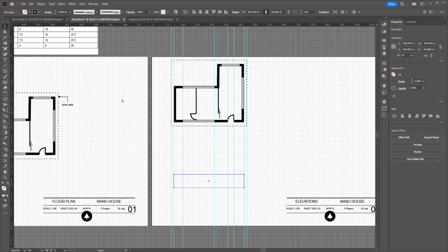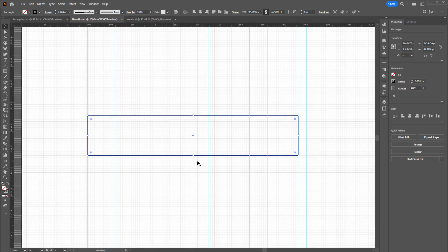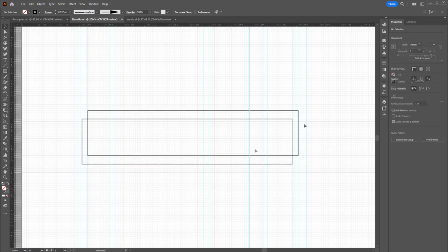And so if I go back down here, and remember at a scale of 1 to 100, the grid line, I should say, for every centimeter is a meter. So we can determine that 2.7 meters, I should say, is approximately there if we were just to feed off the information from the guidelines. So that's a pretty good estimate. I'm going to run with that.